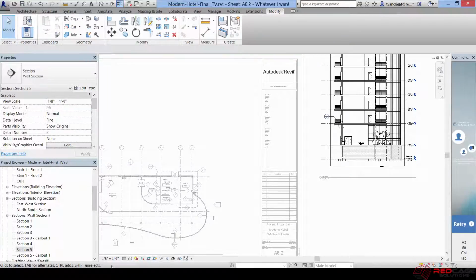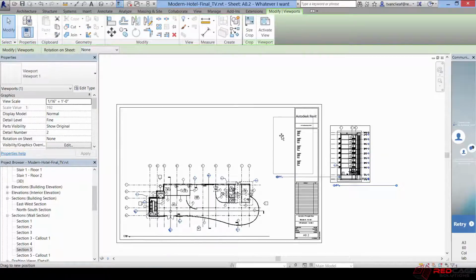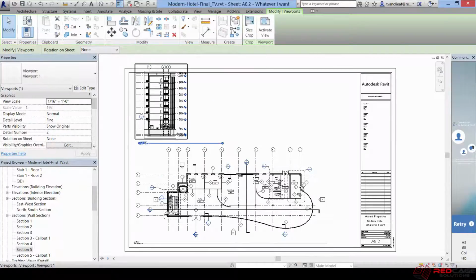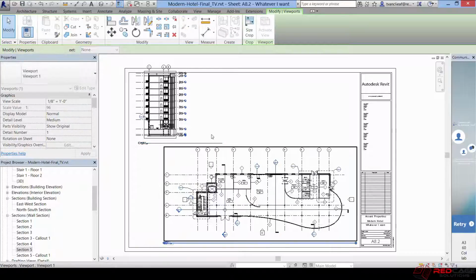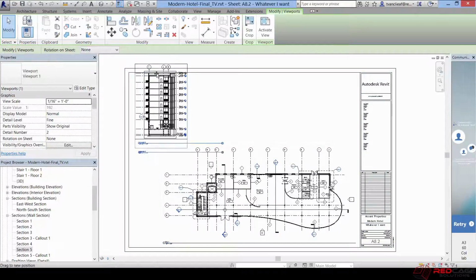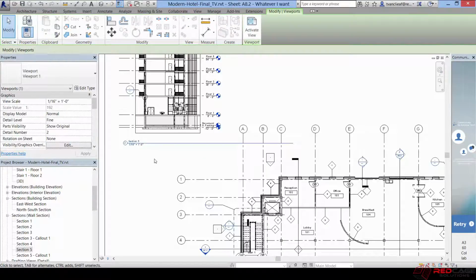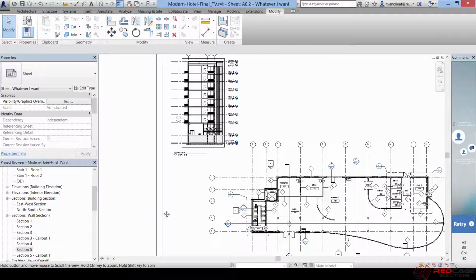double click, and now I can change that to say a 16, and it'll fit on the view or on that sheet. And if it doesn't, there are things that you can do to resize these as well. Like I could shift this around and place this over top, and then by selecting just the view title here, I can modify it so we're not actually having any overlap.